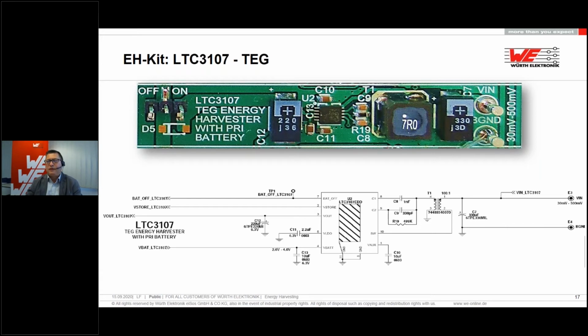And now Würth Elektronik made a good product, this kind of small transformer. Actually, we say this is an inductor special for energy harvesting, and it's a 1 to 100 small transformer. As soon as the 30 millivolts come here, it is amplified by 100, goes to the IC, and the IC starts to operate. But wait, DC,